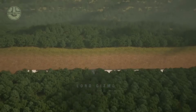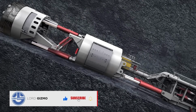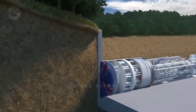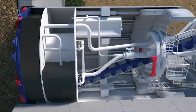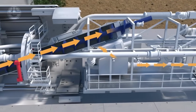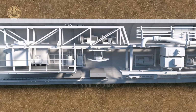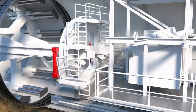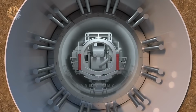A tunnel boring machine, TBM, is an engineering marvel that seamlessly integrates mechanical, electrical, and hydraulic systems for efficient tunneling. At its forefront, the rotating cutter head chips away at the earth, supported by disc cutters for various geological conditions. The debris is then transported via a screw conveyor to a belt system for removal. Simultaneously, the TBM installs precast concrete segments for tunnel support, using an erector arm to ensure structural integrity. The machine's advancement is facilitated by hydraulic jacks pressing against these segments.